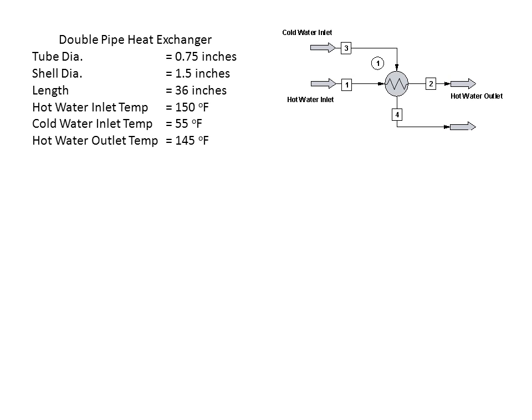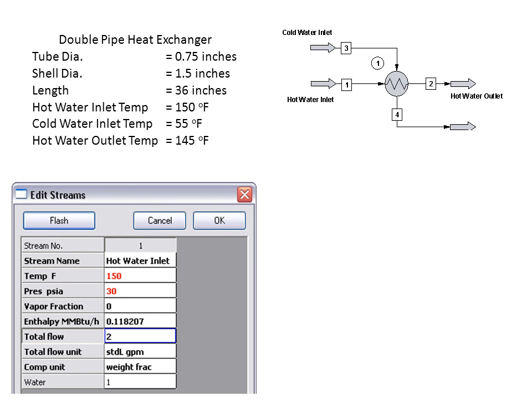In ChemCAD, we're going to use a heat exchanger system where we have a hot water inlet, in my case stream number 1, a cold water inlet, stream number 3. We're utilizing a heat exchanger that allows two inputs, and then we have the hot water outlet followed by the cold water outlet. We input our hot water stream at 150 degrees Fahrenheit.